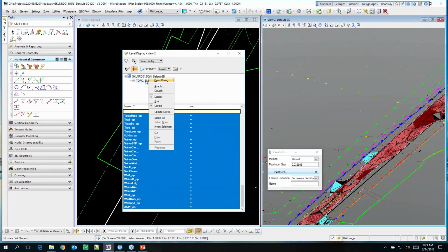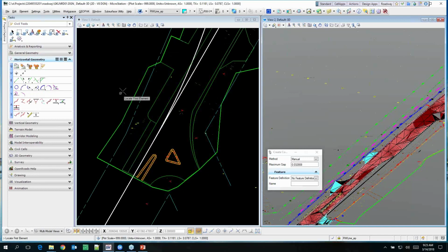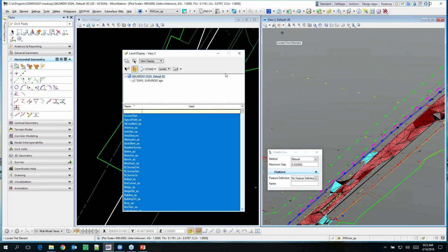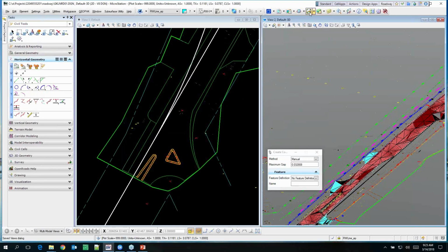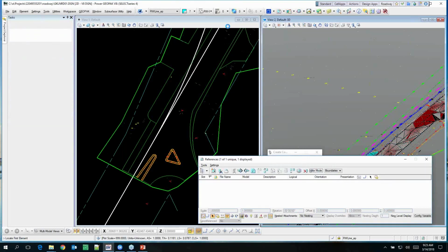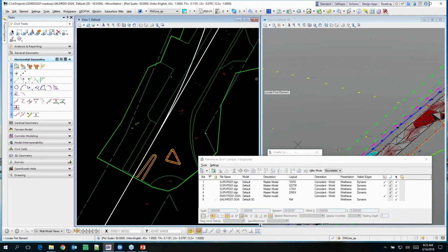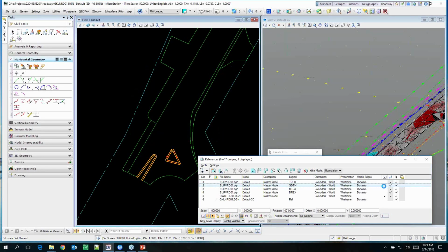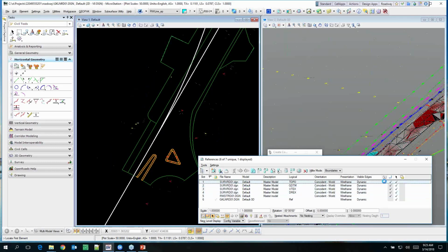Would the profile be the same as just the center line? No, because in order to see the right of way, like on our cross section, we usually like to see right of way lines. You usually draw them as a symbol, either just below the existing ground, or just above it. There's usually a little gap, and it's really just to identify it.